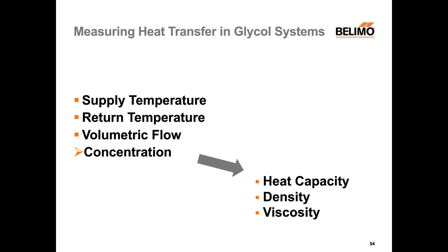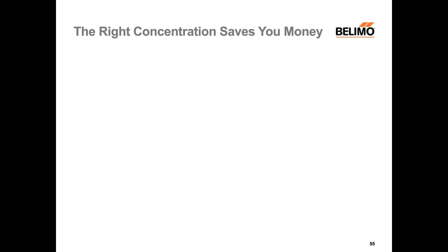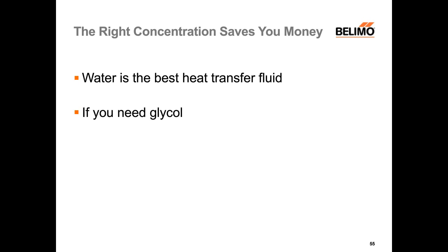Now, the right concentration saves you a lot of money. Water is the best heat transfer fluid. If you need glycol, think, do you really need freeze protection, or is maybe burst protection enough? So, does your system really run when it's cold, or is it not active when it's really cold during wintertime?